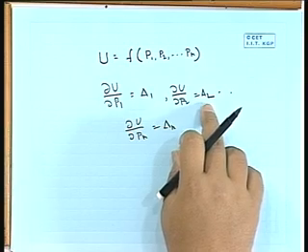Now, if the force is only one P, the energy will be expressed in terms of P, so the partial derivative will be the full derivative, right. So, dU by dP will be delta. What is delta? Delta is the deflection under the load P1. So, delta 1 is the deflection under P1, delta 2 is the deflection under P2.